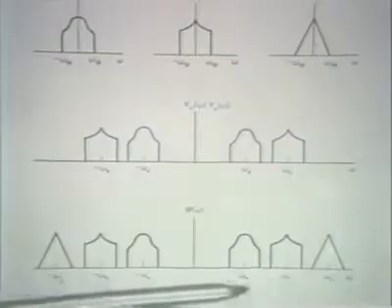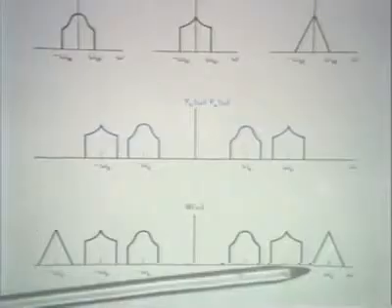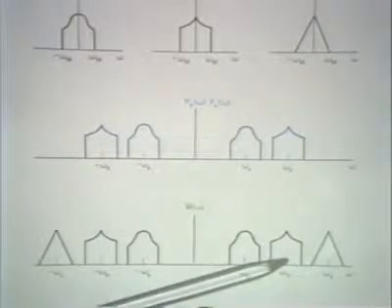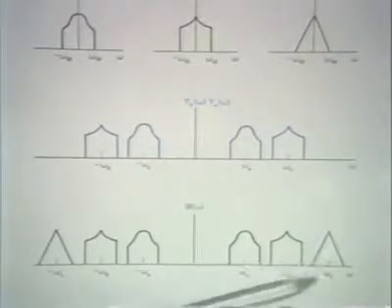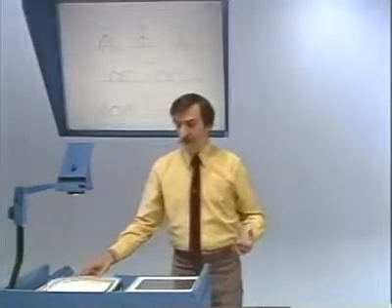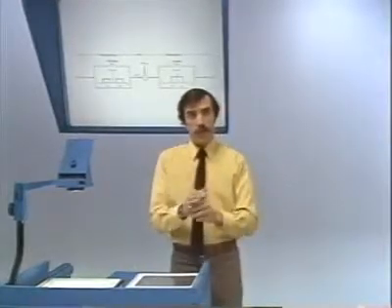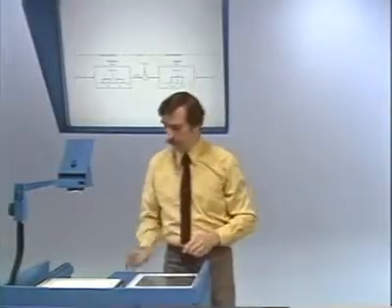And as you can see, essentially, by doing appropriate bandpass filtering, we can pull out whatever part of the spectrum we choose to and then demodulate that in the appropriate way. And of course, we can do this not just with 3 signals, but perhaps with tens or hundreds of signals. So that's a process that is typically referred to as multiplexing. And as I've described it here, it's referred to as frequency division multiplexing. That is, dividing the frequency band into cells and plunking different signals into each one of those.